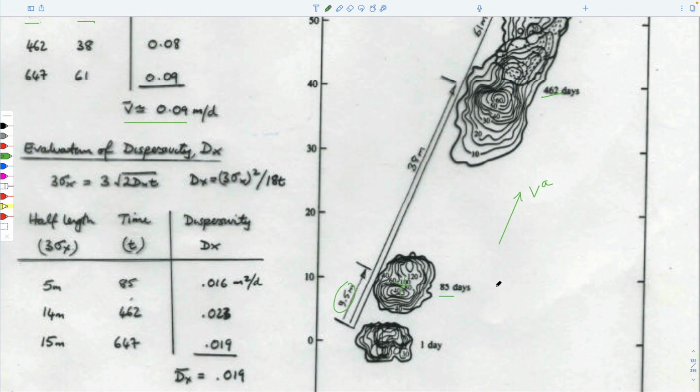We know what we talked about last time, the geometry of our plume. If we look at it in terms of, actually I didn't really want to draw this upside down, but if we draw it in terms of a Gaussian distribution, it looks like this. Bad drawing. This is 3 standard deviations, what we call 3 sigma, and it's a physical length. The half plume length is a length. This is C over C0.